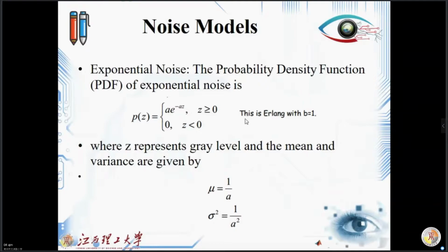If we go further in the noise modeling part, we have another form which we call uniform noise, in which the probability density, or PDF, of the uniform function is 1 divided by b minus a. It becomes a little bit simpler than the Gaussian one. Now you will see the difference is that you don't have the exponential term here. And again, mu is the mean and the variance formula uses the parameters a and b.